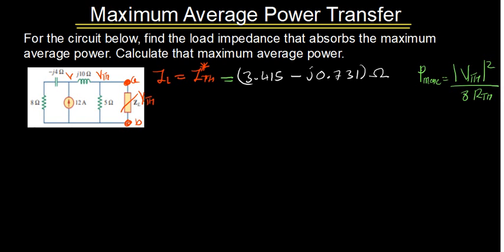So here I'm going to put a voltage there and indicate it as V. Then I'm going to ground this part, and we know that on the ground the voltage is 0. So I'm going to put up currents. Remember, nodal analysis is simply KCL, Kirchhoff's current law, where you use the currents to find the voltages, unlike KVL, where you use the voltages to find the currents.